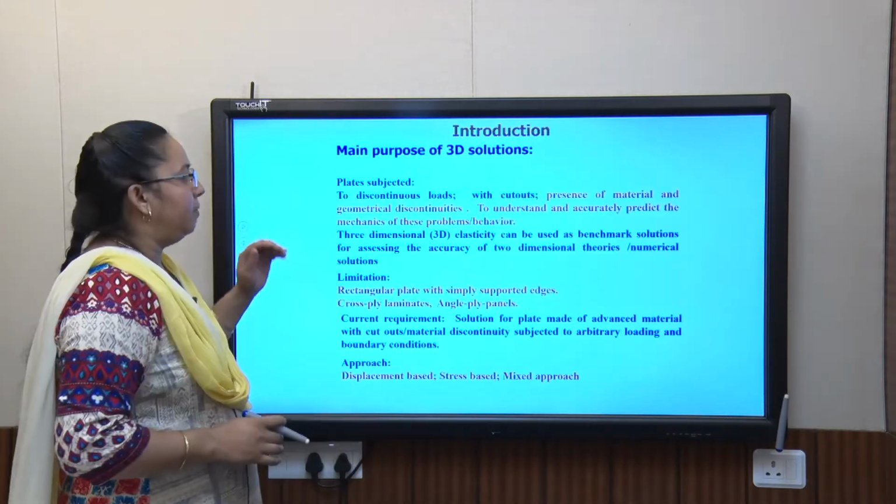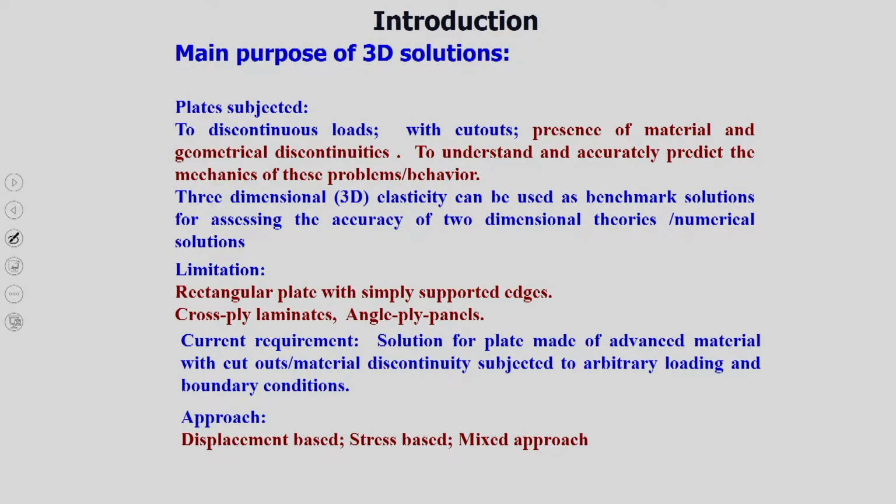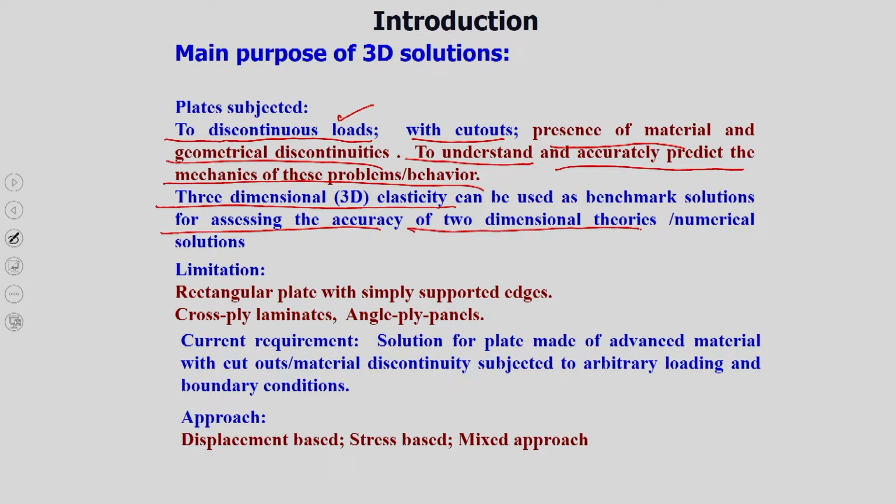The main purpose of 3D solution development is that a plate is subjected to continuous load with cutouts or the presence of material and geometrical discontinuities. So, to understand and accurately predict the mechanics of these laminates. This I am saying again and again. And the next very important point is that these 3-dimensional elasticity solutions can be used as benchmark solutions for assessing the accuracy of 2-dimensional theories or numerical solutions.